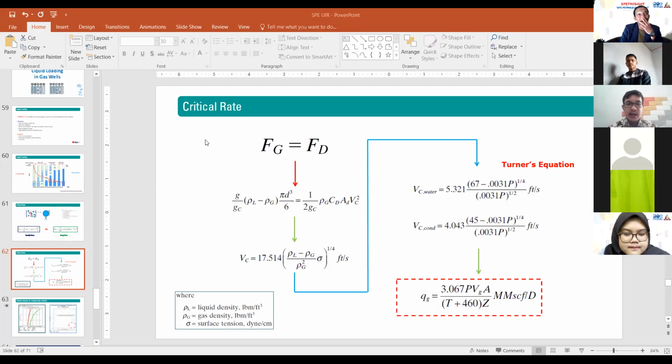They record the data continuously, and they will know whether at one point you will face liquid loading. As you can imagine, they know the wellhead pressure and the temperature. You have also already input the tubing, the well configuration, and the flow line configuration, and the gauge measures the wellhead temperature, wellhead pressure, and the flow rate. So by giving the machine learning or artificial intelligence training and learning, like a neural network, it will predict whether or not you will face liquid loading.